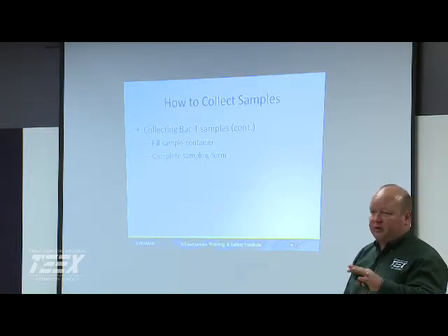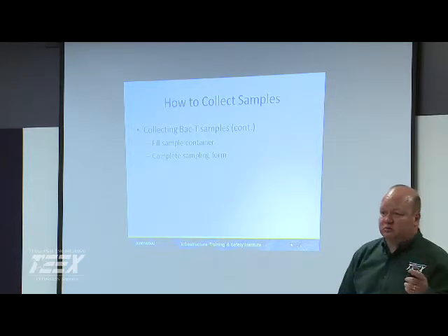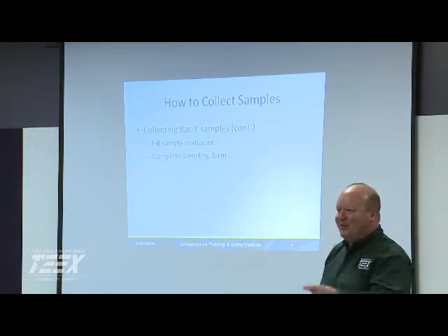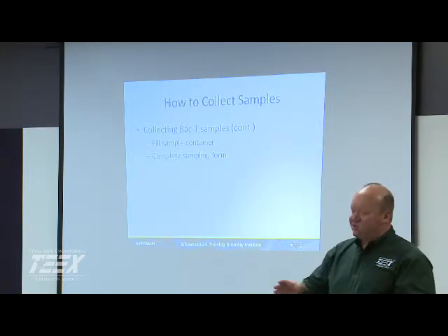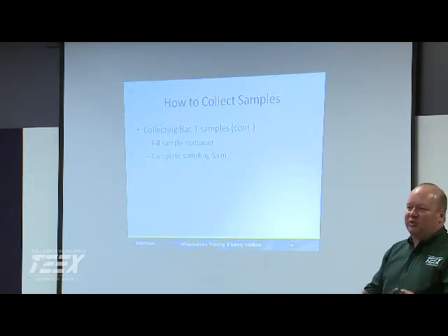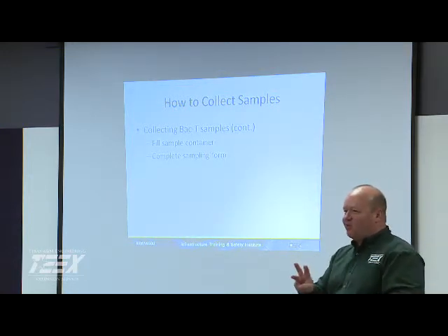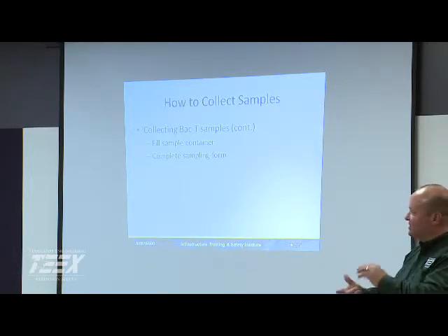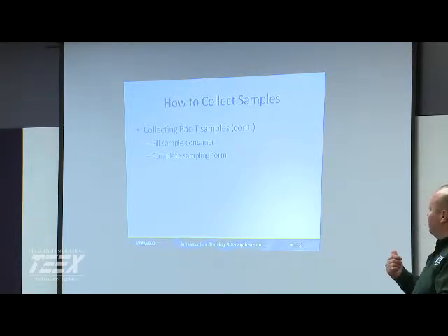When we fill in the sample, we're supposed to pull how many mils? 100 mils plus or minus about 5. How many times do we rinse the bottle? Zero. Right? It's interesting, a lot of times you say, oh yeah, you rinse it a couple of times. No, not those samples. In the lab, normally when you're doing certain types of sampling or testing, 3 rinses is the norm. Not for bacteria tests, not for anything that's been preserved, lead and copper, things like that.